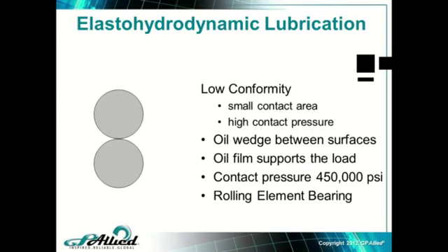When the oil wedge passes, it compresses. When it goes by, it pops back out. Right? So elastohydrodynamic. Associate the word elastohydrodynamic with rolling element bearings. So we still have the oil wedge. We still have the oil film, lubricant film, keeping the two metal surfaces separate. So it works the same in a gear as it does in a bearing.